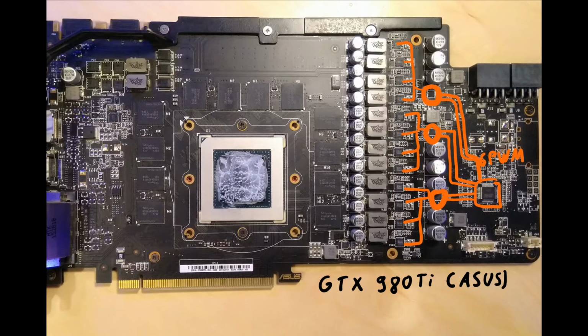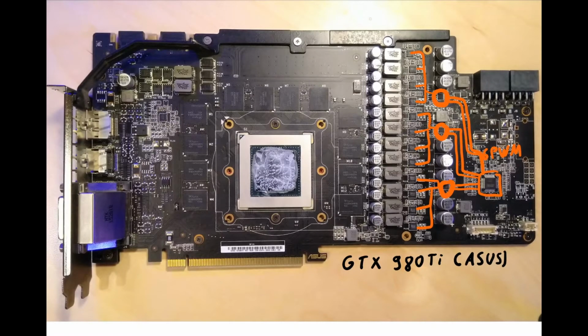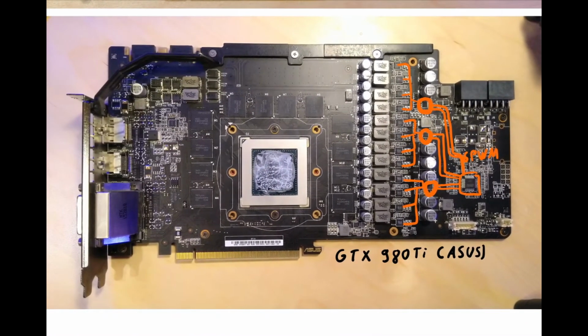This is better than just having a 6-phase, but for the PWM controller you only have 6 phases, and it's up to the doublers to determine how the VRM is handled. So some doublers maybe just send the information for every other phase to the PWM controller, or they split the information up between them. And yes, if you have doublers, the PWM controller lacks information basically. It doesn't really know what's happening. It will be slower to respond to changes in voltage and such things. But it is still a lot better than just a 6-phase.